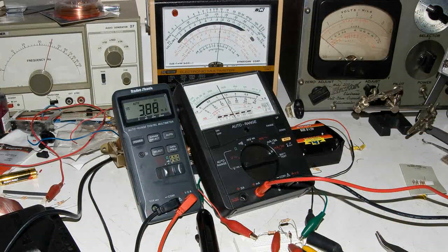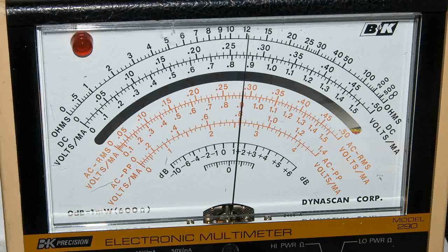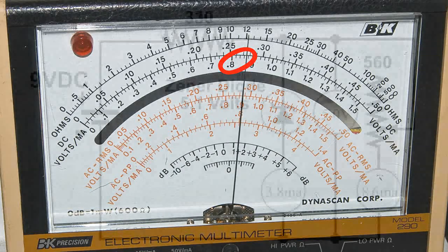In this second clip, we saw that when I put a load resistor of 560 ohms in the circuit across the Zener diode, we get about 3.8 milliamps through the Zener diode. We still have about 5 volts across the Zener diode and the load resistor is now drawing 8.6 milliamps.